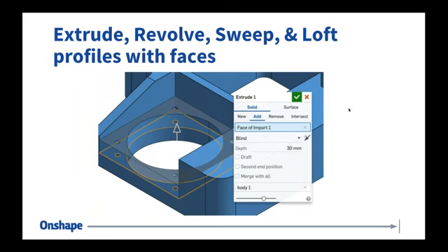All right, so this is again just the extrude, revolve, sweep, and loft command. It's the command that not many think of when they think about working with imported geometry, but it does work, right? So if you need to offset faces, or you need to do a swept path, as long as you have reference faces or things to reference from the imported model, it should work just fine. And again, the key thing to stress, as mentioned earlier, this is specific to solid models. Surface modeling is a different thing entirely.